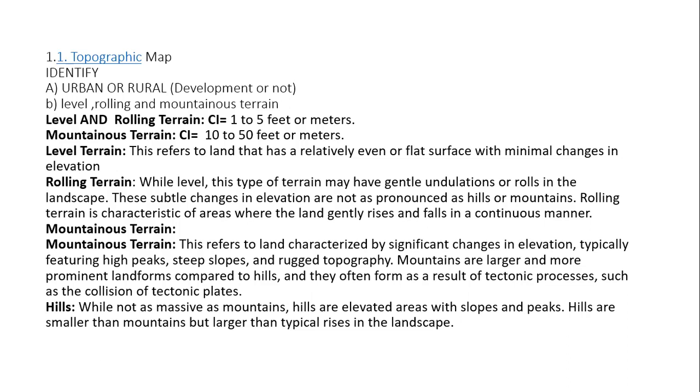In the rolling terrain, the car is not going to change the gears while the heavy vehicle has to change the gear. That is a rolling terrain. And for the mountainous terrain, both have to change the gear, but the performance of the heavy vehicle will be slowed down, and its engine may not be able to get that speed because of the terrain condition. And these are the definitions.